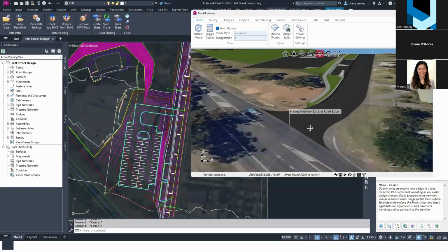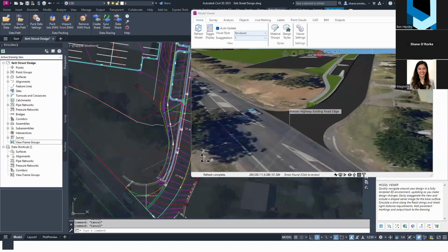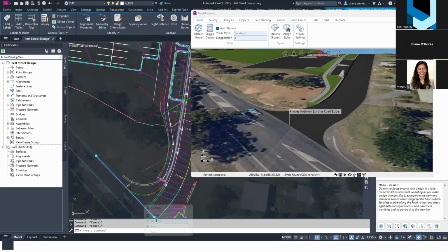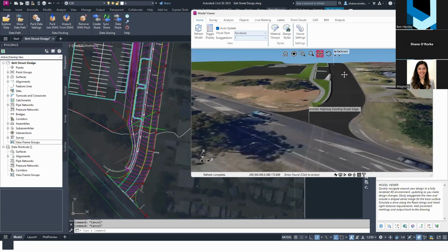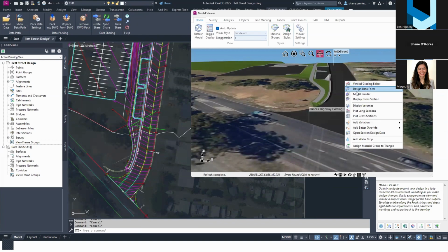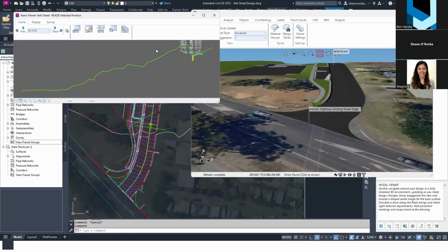What I actually did with this project is I created an alignment here for an existing road. Underpinning this there's an alignment hiding under here. I created a centerline alignment, and left and right alignments, for this street called Islet Street. The intention with Islet Street was to reconstruct that road. When I open up the cross-section viewer for this particular string, I'm still in a cut zone, but as I roll along my cross-sections, you'll see that my goal was... roll through fast enough.